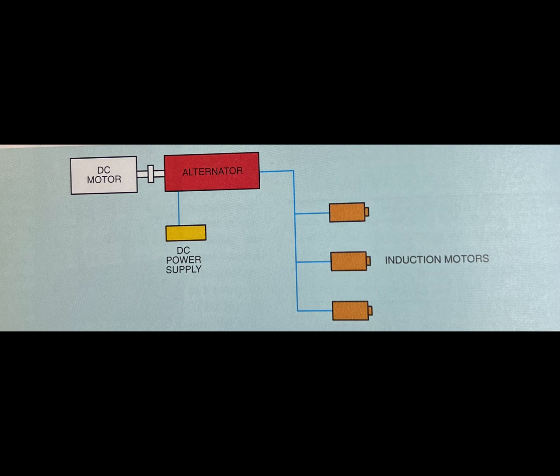As current flow is decreased, the magnetic field of the stator becomes weaker, and the increase in rotor slip causes the motor speed to slow down. The motor speed can be adjusted by changing the tap with the rotary switch to insert more or less of the inductor winding in series with the motor.